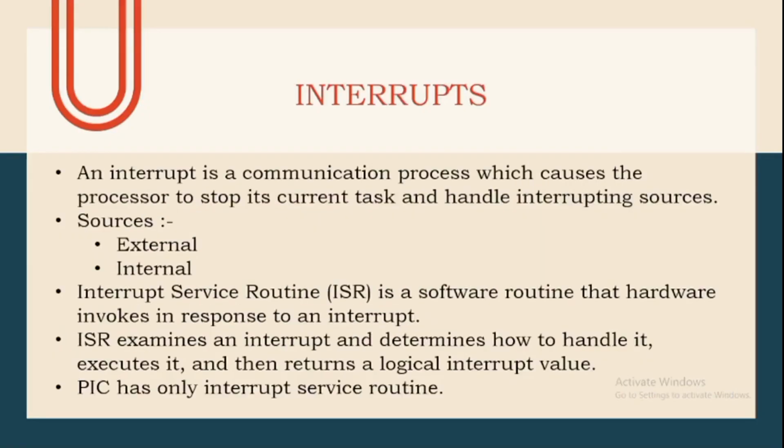And coming to the next slide, interrupts. Interrupts allow the microcontroller to pause the current task and give priority to urgent inputs. We use the interrupts in our simulation to mimic real safety mechanisms. For example, stopping the motor when the washing machine door is opened during operation. PIC uses ISR, meaning interrupt service routines, to manage these events.